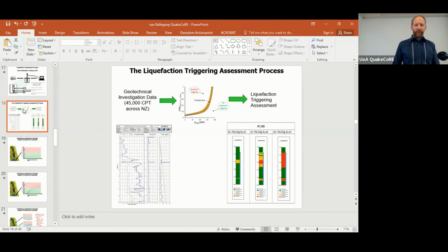Yes. I have shown a very simplified version of this presentation. It is more detailed. The simplified procedures do make corrections for your fines composition. The more fines there are in the soil, the more correction that is made.